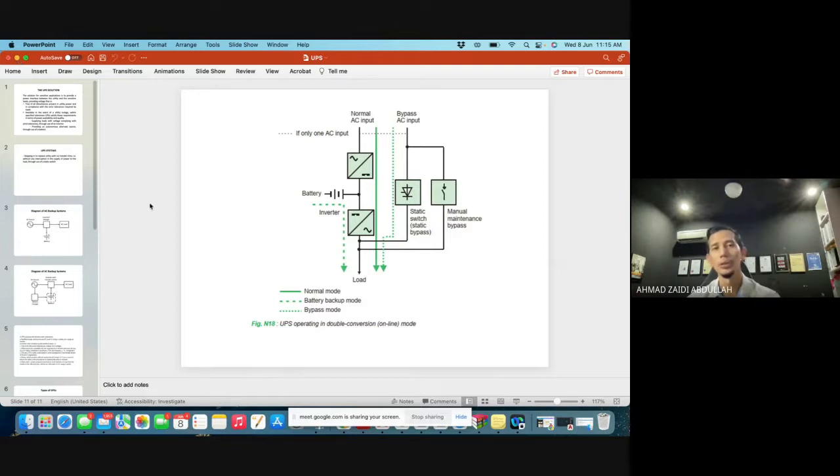Okay, how to size it. You get the value of your load to back up, and then you add 20% up to 30%, let's say. Suppose you want to add 20%, okay, you want to add 30%, okay. In the standard it says 30%. Normally JKR just adds 20%. It is the same as your DB design. For your DB you add spare of 20% up to 30%.